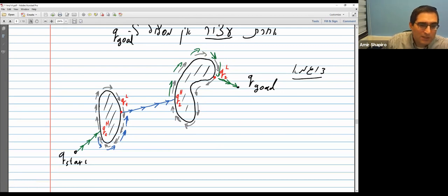When I finish the circle, I find the point along the boundary of the obstacle which is closest to the goal. I go back to this point along the shortest way around the obstacle, and from here, I go directly to the goal.